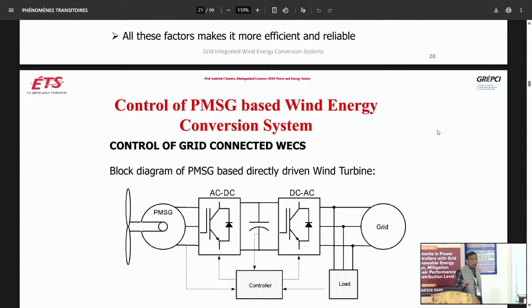converter. It is basically the same type of thing which we have seen in active filters yesterday and the day before. What did we say about the shunt active filter? One objective of the shunt active filter is to keep the DC link voltage constant. So how will it keep the DC link voltage constant? It will transfer the power from the DC link to the grid. And then on top of that, this converter may work as a filter also, a power conditioner also.